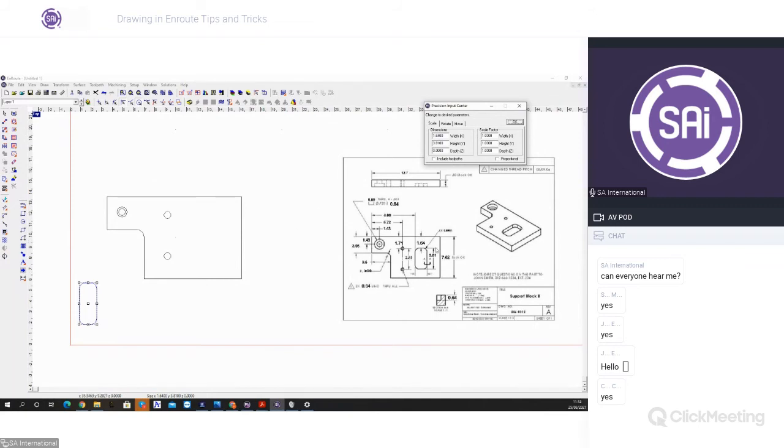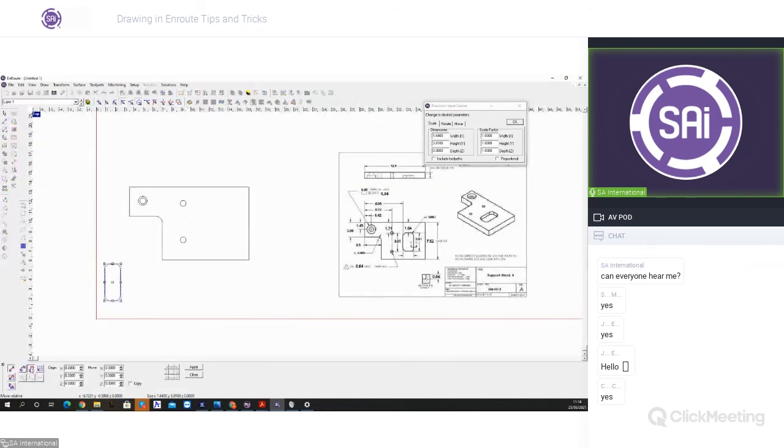And then actually we can move this in the same way with the snap tools as well. So we'll snap to endpoint. So we can go here and move objects, move them relative, or we'll actually move corner right here. We'll select the top left corner, and then we'll just make it snap onto the corner right here.